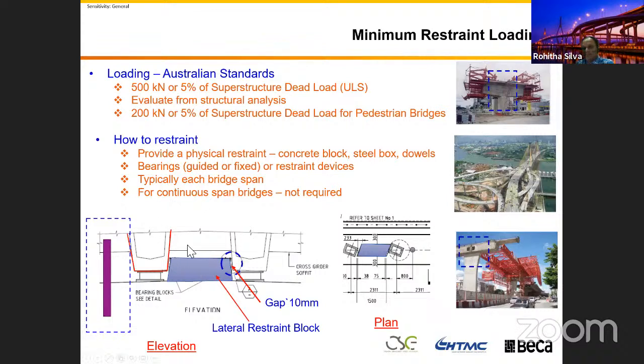This system is quite important. Providing a lateral restraint block will help you, because the bridge can be subjected to significantly large lateral load, and you don't want to worry about your bearing moving. A lot of designers and people argue that bridges are so heavy that the friction between the bearing and the bearing surface and soffit of the girder is sufficient to restrain it.